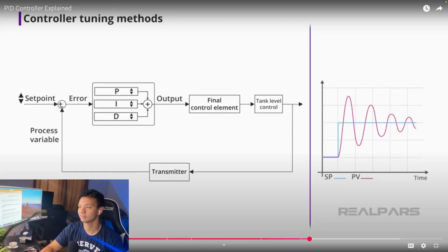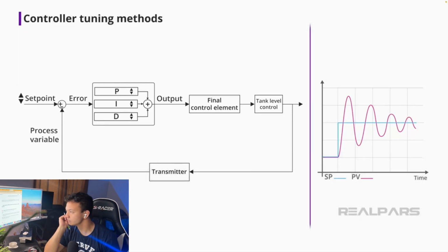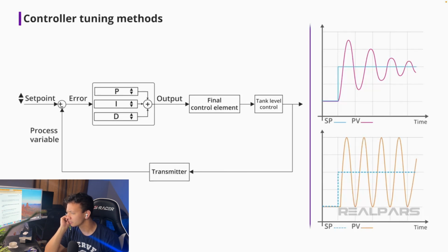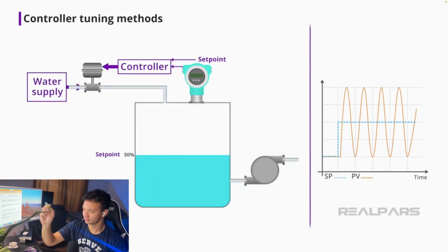One method involves increasing the amount of set point change and repeating the procedure until the process enters a state of steady state oscillation. This method of tuning produces adequate results, but is often impractical in many applications. For example, how practical is it to force the fluid level in a large tank to reach a steady state oscillation?